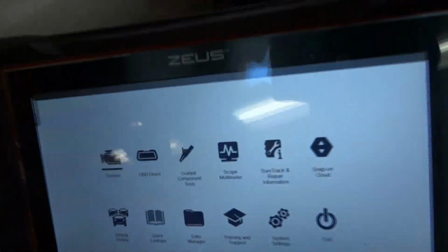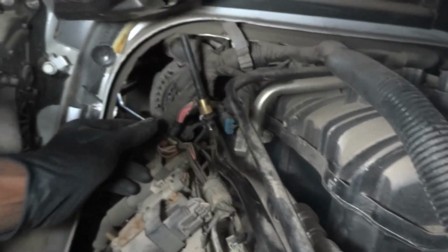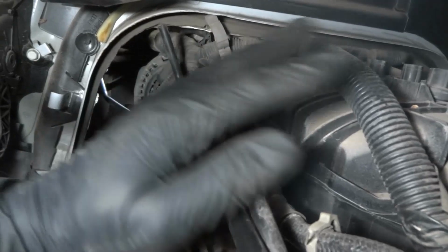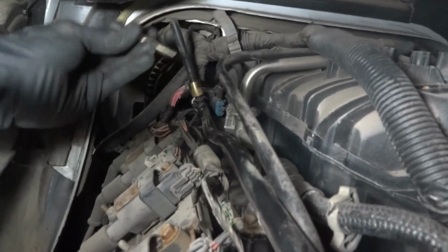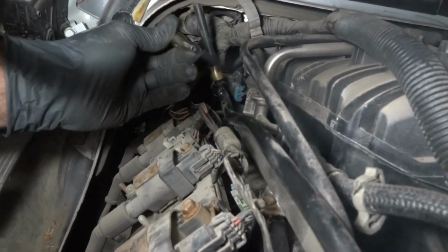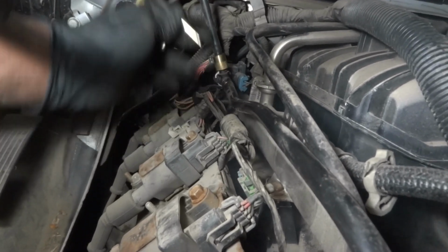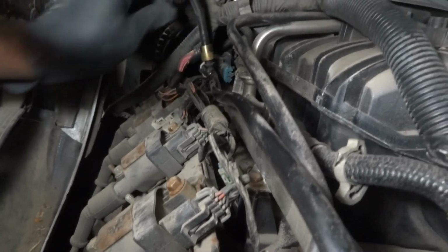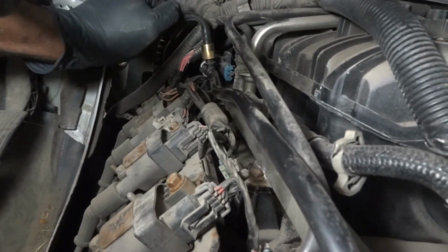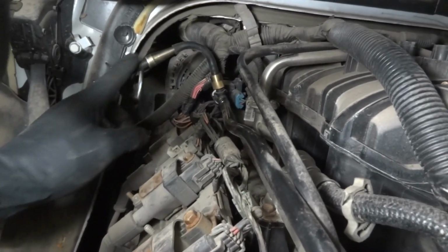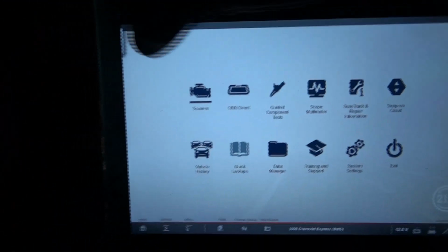We're now gonna go inside the vehicle. Okay, so we can connect our supply line of the smoke machine to the service port over here. Okay, so it's a lot easier when you remove the engine cover. So now I'm gonna connect this tube. As you can see, there's smoke over here. So I did remove the schrader valve that goes on the service port over here. So now we're gonna connect this. Okay, just like that. So now we're sending smoke inside the evap system.